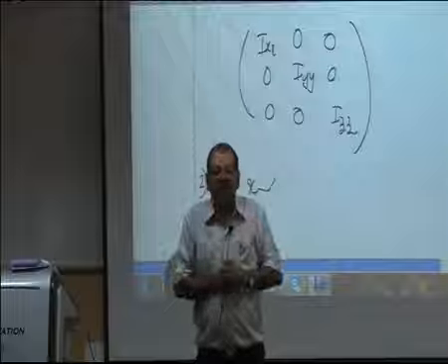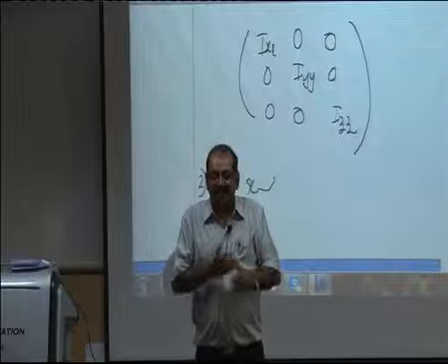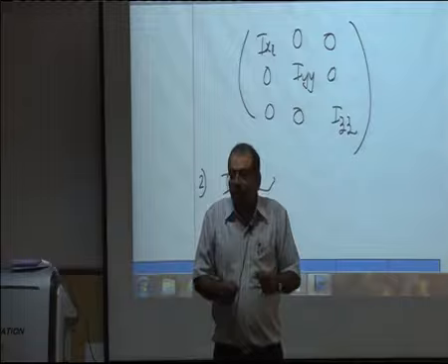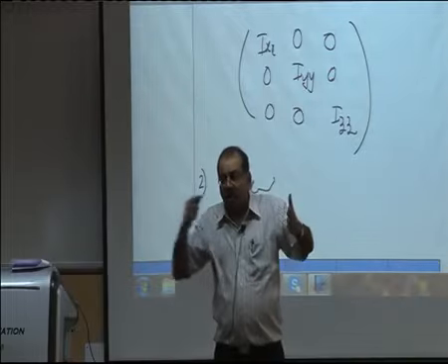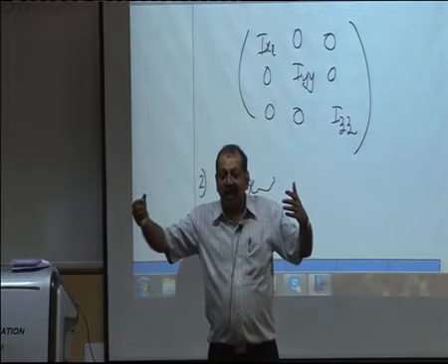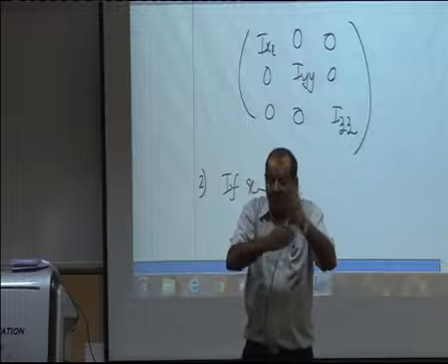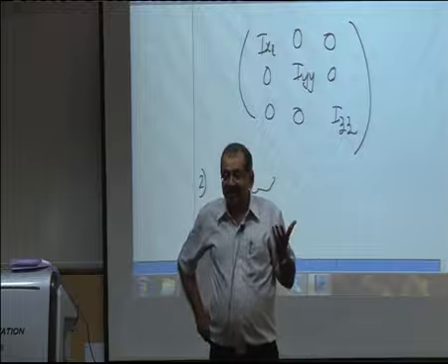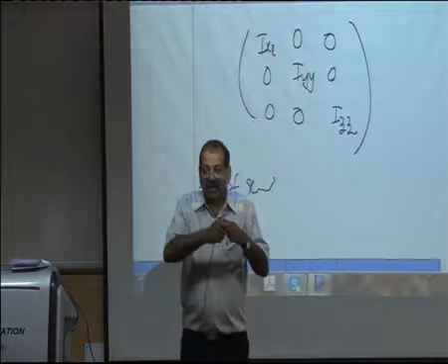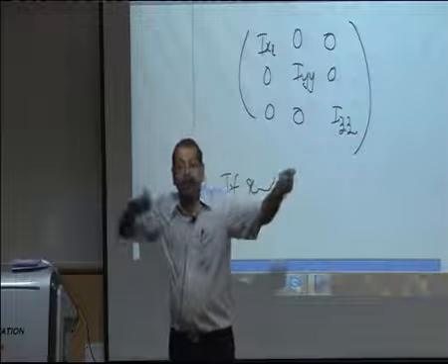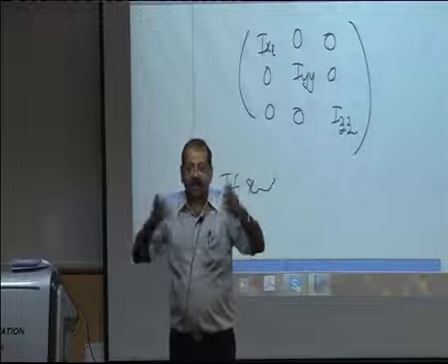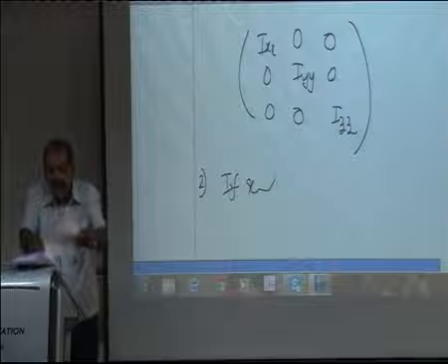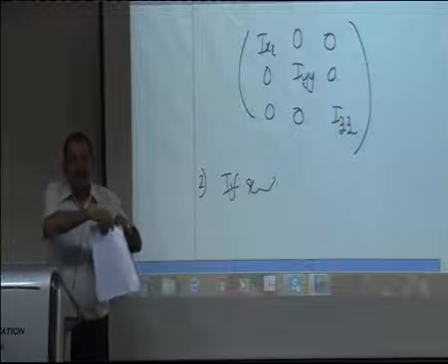So, if there are 2 planes of symmetry, what happens? The line which is cutting the two planes will be a principal axis, and the perpendicular to each plane will also be principal. So in the plane which is common to these two planes, all the axes will be principal axes, because at that intersection one of them will be a principal axis and the perpendicular to that will also be a principal axis. So therefore all three will be. I will show this symmetry discussion in the next class.